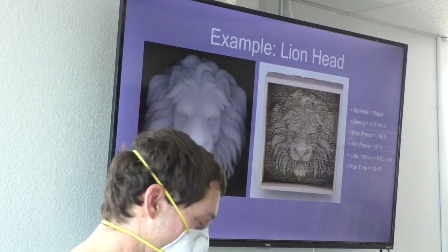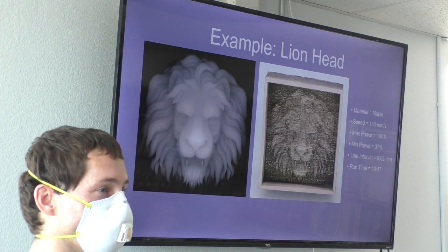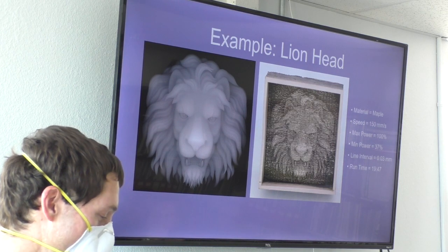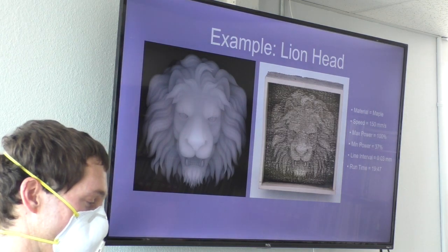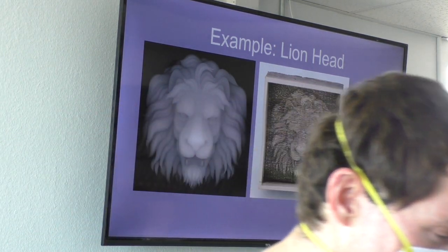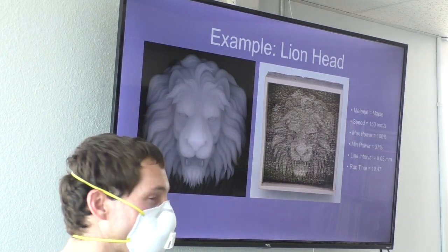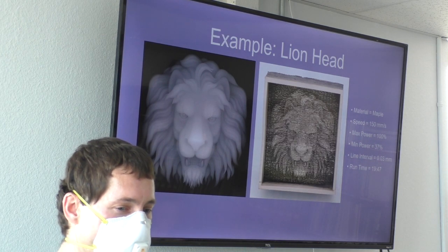Then we've got this guy who's a lion, and one thing to note as you pass it around: on all the pieces that have a dark edge, I cut those on the laser as well. This one I attempted to cut, and I don't know if it was because the piece was so narrow it was trying to bend a bit and hitting the laser badly, but it had a lot of burning on the sides that it shouldn't have had. It took like 3 passes to get it cut finally. I think it's somewhere between 3/4 and an inch thick.